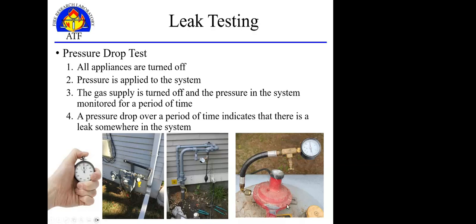This picture on the right was actually at my own house. I just had new regulators I put on this summer. My second stage regulator was actually leaking. So the gas technician had this little gauge, kicked it up to 6 psi. We had turned everything off, let it sit, and you could see here it started to leak in just that 5-minute span, so we weren't holding pressure. So we had an issue with my second stage regulator.